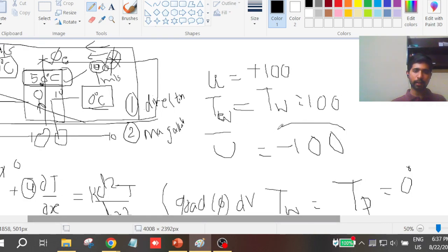So again, that is what I was telling, you have to take into account the flow direction and the magnitude both. Now I am just telling this in a very vague manner. There should be some technical aspect through which we can determine whether I need to do direct substitution of temperature, or should I do a linear interpolation.